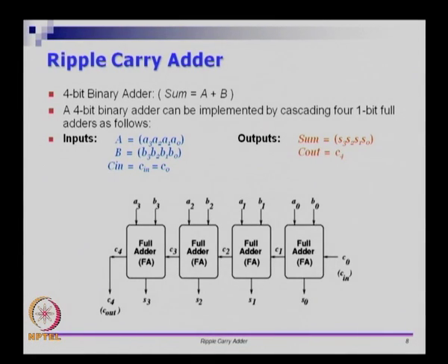Let us see how this will be built. You take a full adder and you give A0, B0 to it. If there is a carry input, you give C0. If there is no carry input, you put a 0 here. This will give you sum naught and a carry 1. This carry goes as the next stage carry. This is what we do in decimal addition also, right. So if in the ones position I add 2 numbers, the carry from that will go to the 10th stage. So if in the 10th stage, whatever carry comes out will go to the 100th stage and so on.